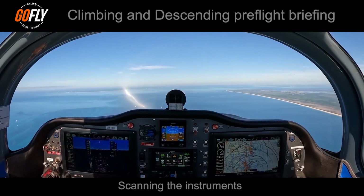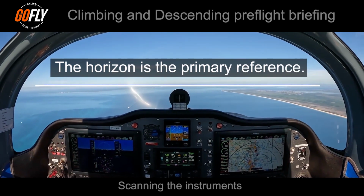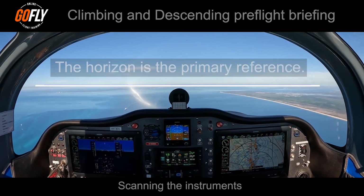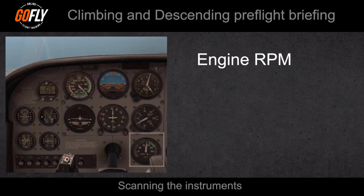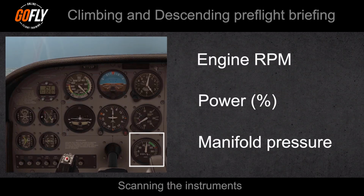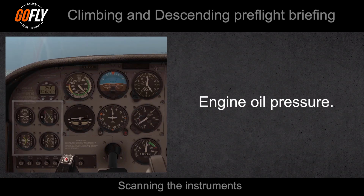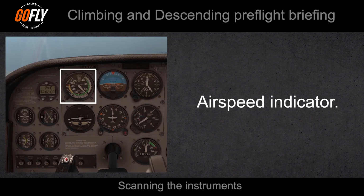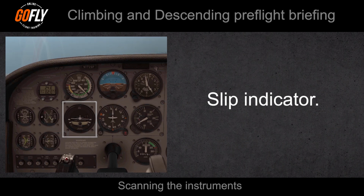When climbing and descending, the pilot's eyes should be on the horizon for the majority of the time, the horizon being the primary reference. However, we also need to use the aircraft instruments for better accuracy and engine monitoring. Some of the instruments you may use are engine RPM, power and manifold pressure, engine oil temperature, engine oil pressure, airspeed indicator, altimeter, VSI or the vertical speed indicator, slip or balance indicator, artificial horizon.